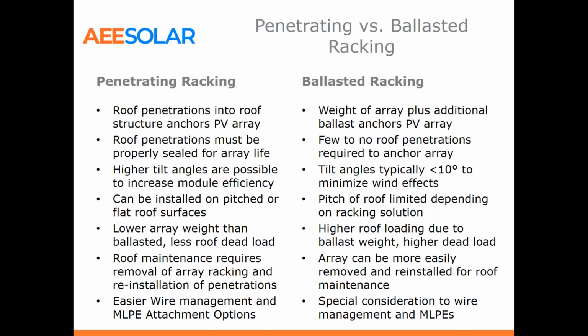Pitched roof surfaces, there are some penetrating racking systems that can pitch up on a flat roof surface. Typically, we get much lower array weight with penetrating racking. So if the roof is limited in the amount of dead load it can handle, penetrating racking would be a choice there. Roof maintenance, though, requires removal of the racking and then reinstallation of the penetrations. And sometimes your wire management is easier with a penetrating rack and railed system because you're attaching and using the rail to help with the wiring.